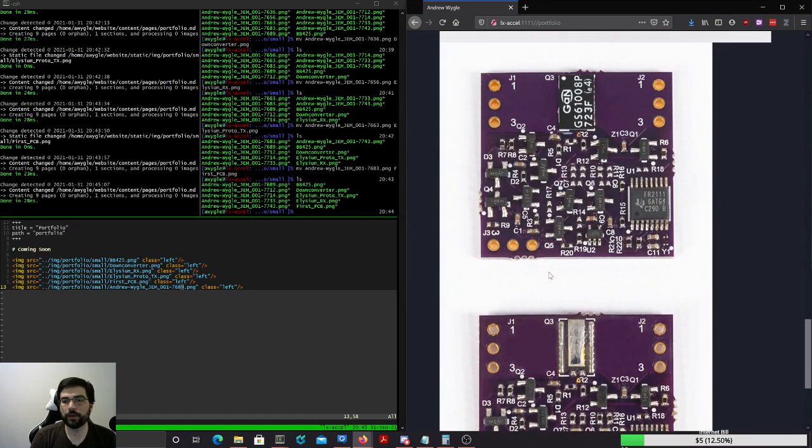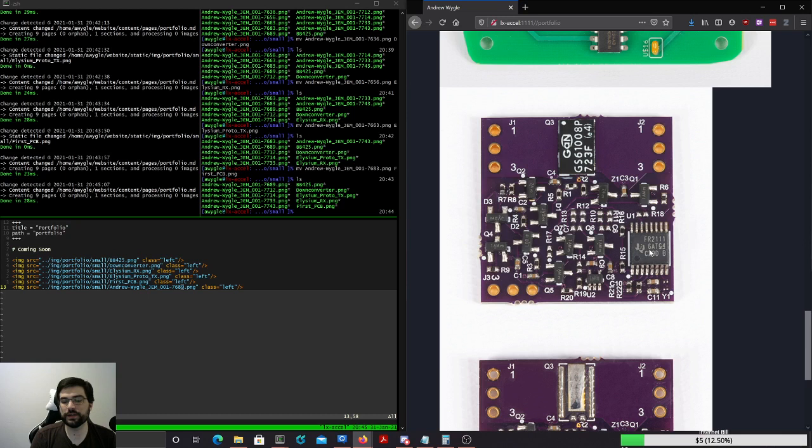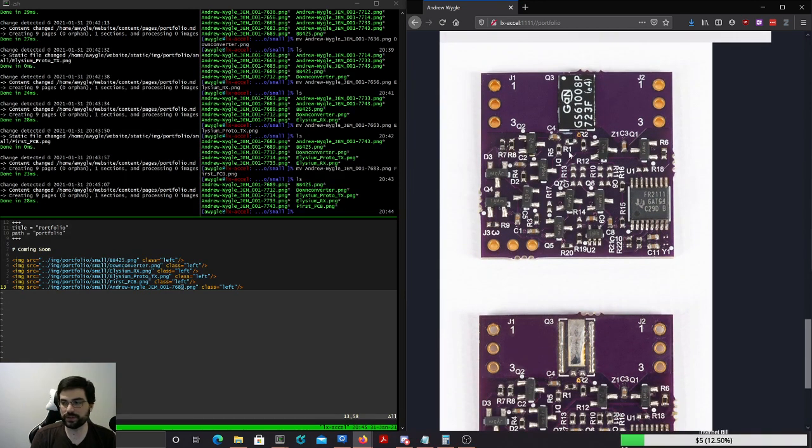Ooh, so this one's fun. This is the same converter board but populated differently. It's a PFET driver for a GaN FET. So GaN FETs, gallium nitride is GaN, G-A-N. And GaN FETs are really interesting for a lot of different reasons. They can be very efficient. They have low switching losses. They, in theory, have 0 reverse recovery losses, a bunch of other weird stuff about them. But the main point of interest, in my context, is that they are extremely radiation tolerant. Instead of having gate ruptures and total ionizing dose problems that weaken the crystal structure of your silicon, gallium nitride is much more resistant. Gallium arsenide also, but to a lesser degree.